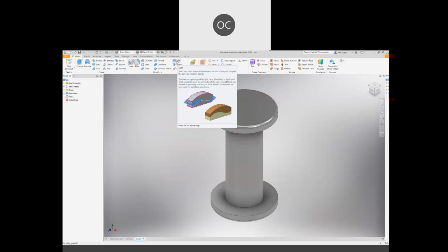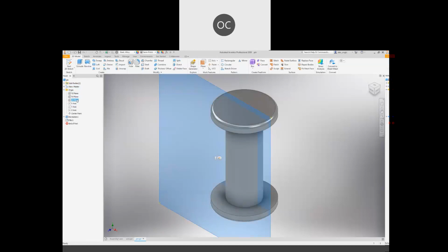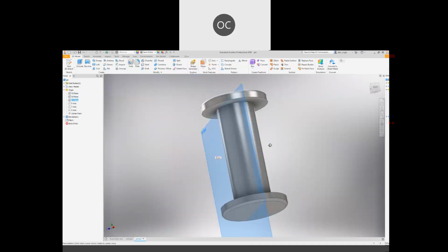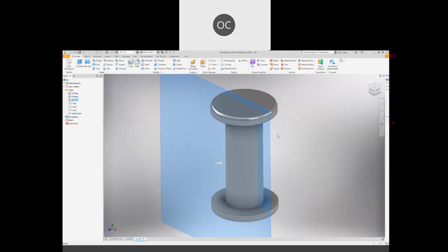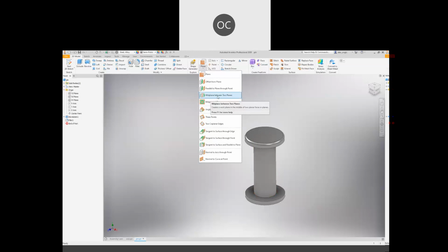Okay. First of all, you would like to ensure that on your plane here, do you have the middle work plane? We will check on the plane because we need a surface to split. This is half here, which is not very useful in our sense. So you need to create a middle work plane in between this top and bottom surface. So hopefully you still remember, go to plane, or you can go mid plane here directly.